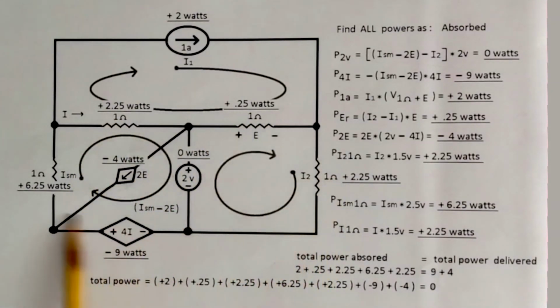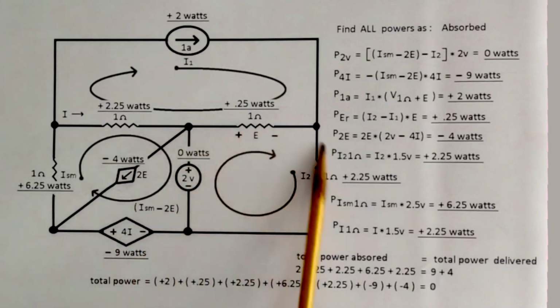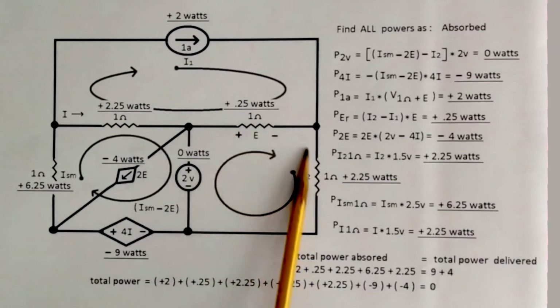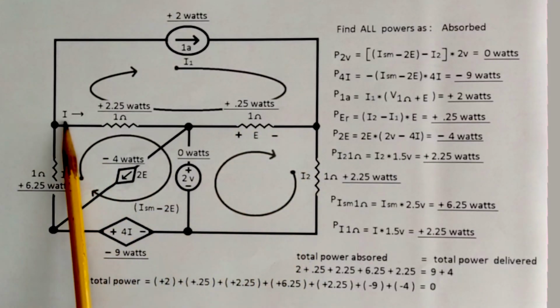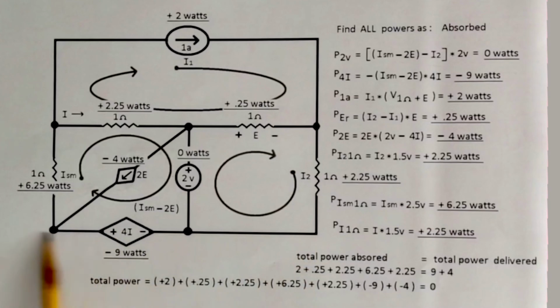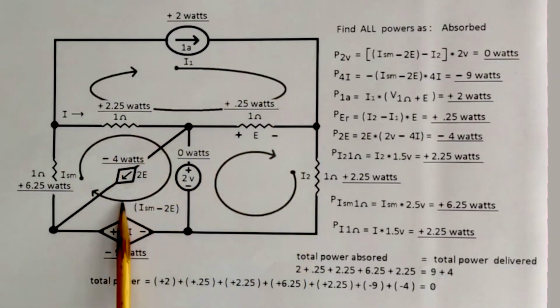If you've ever worked a 2-loop supermesh with the current source in the middle, we see the supermesh path, because we can't write Ohm's law for the current source here. If we define the supermesh here going across a 2-loop standard circuit, we would say, oh, this current here, if it was going up, it would have been added to this supermesh plus this current, and that would be the current over here. It's another way to do it. We can actually use a real supermesh current, or we can just identify the supermesh path and continue to use standard mesh currents. But then again, in the end, we will need to substitute the value of a current source back into it. So this 3-loop circuit, it's the same thing.